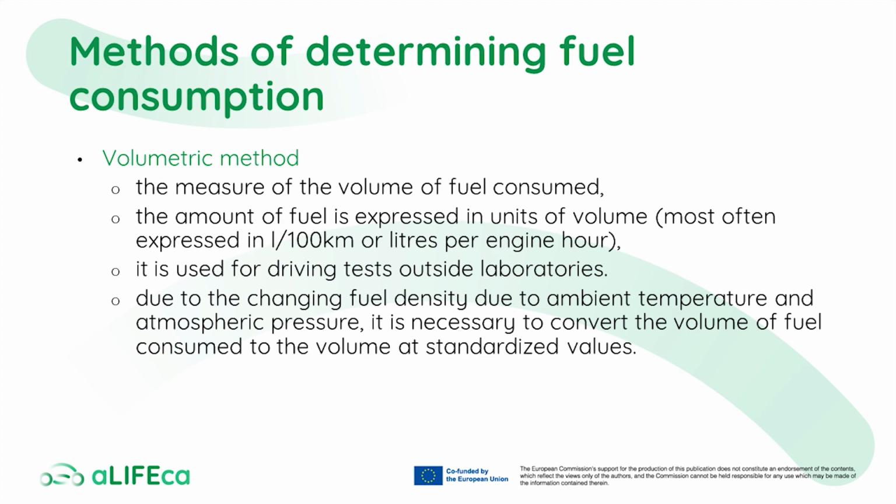This method is more flexible due to the measurement procedure and the instruments used. Therefore, it's used for driving tests outside laboratories. Due to the changing fuel density caused by changes of the ambient temperature and atmospheric pressure, it's necessary to convert the volume of fuel consumed to the volume adjusted to standardized values.